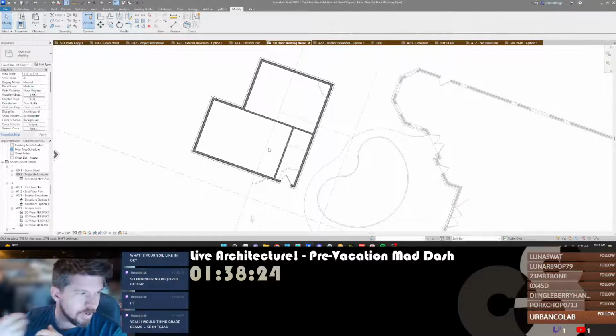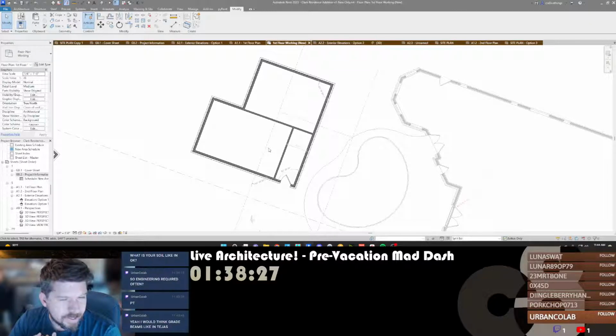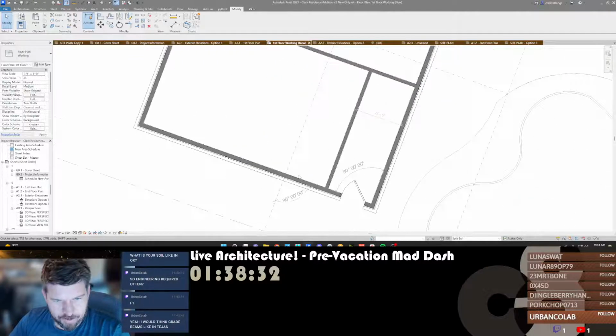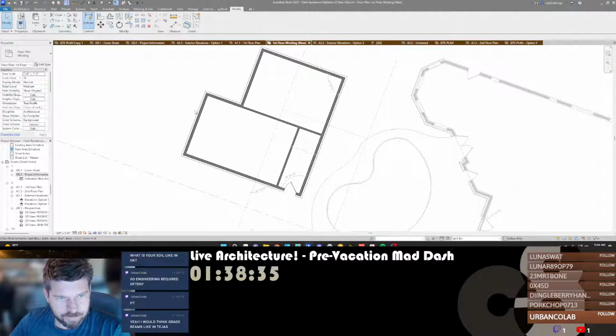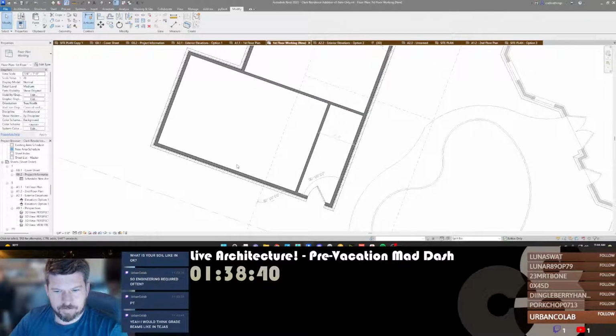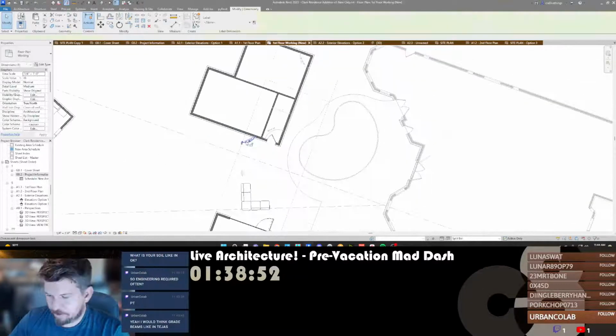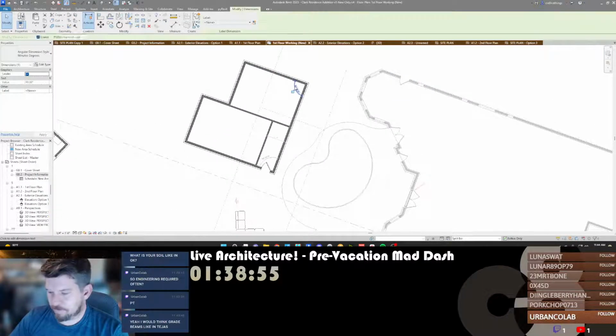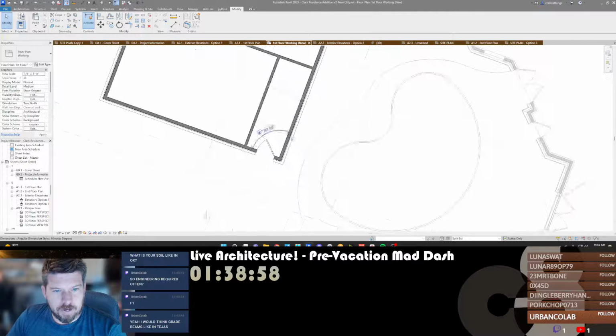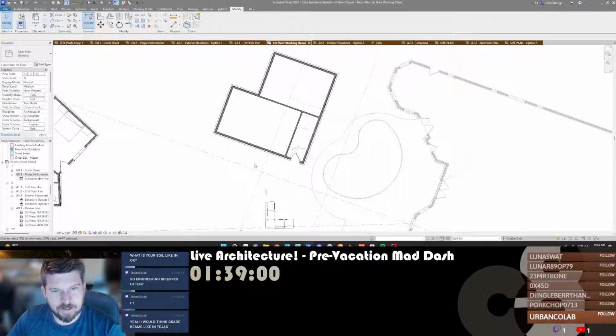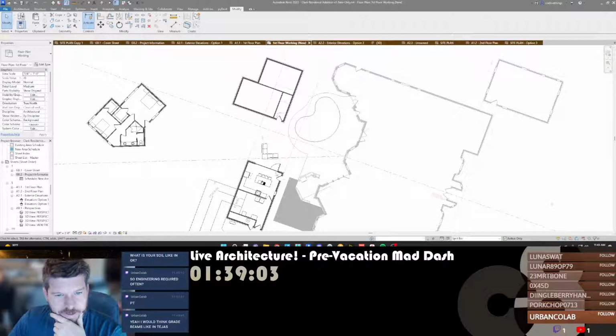Yeah, I don't know why people don't use more grade beams here. I think it's just an expense thing. A grade beam slab's pretty hefty in terms of amounts of concrete. But for sure, right now we're going through a pretty severe drought, so all the soil is shrinking, and I know people are going to have serious foundation issues at the end of the drought. Everyone's going to be pretty busy getting foundations back right.